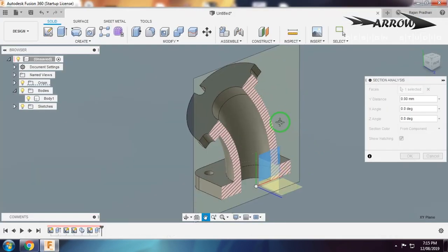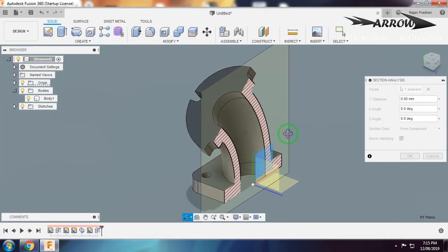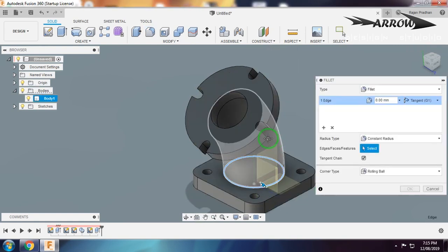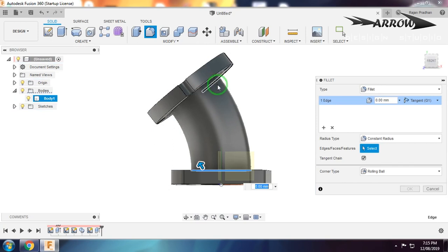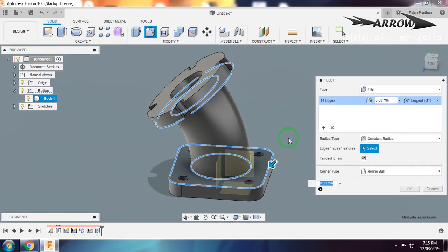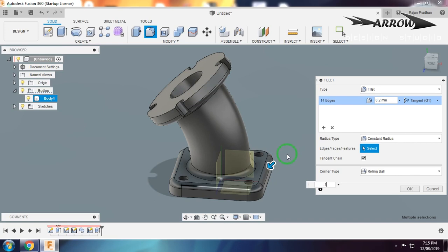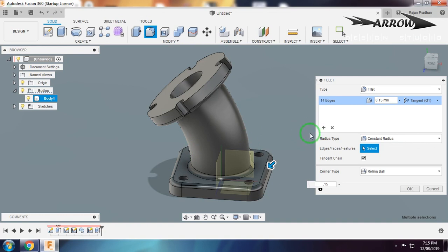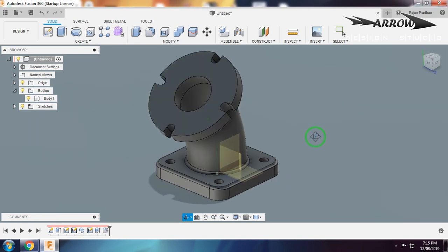And we can have a look at this. Now we'll give the last thing over here. Those are fillets. Press F, enter. This one and this fillet is the crucial one, and along with that I'll select these as well. These are the fillets, and 0.15 is comfortable, because it's not mentioned anywhere, so I have the freedom to choose it. Either you can say 0.1, which is also okay. Say okay. In this way we have done it.